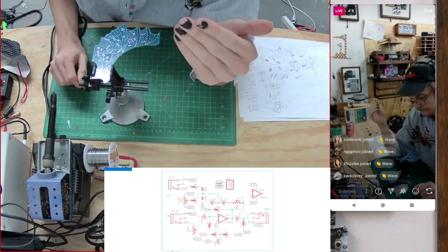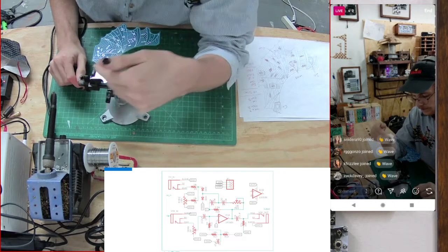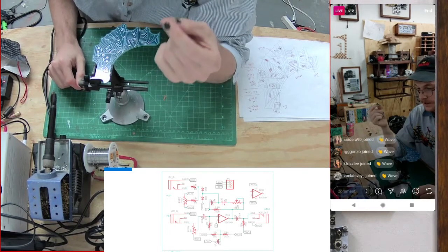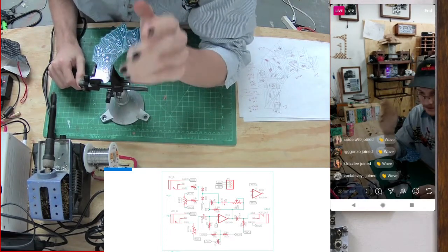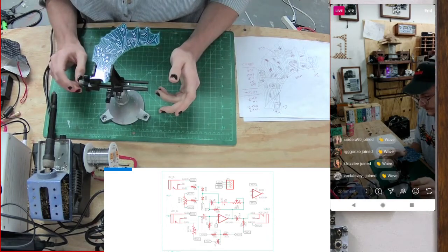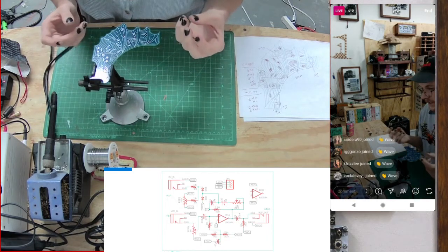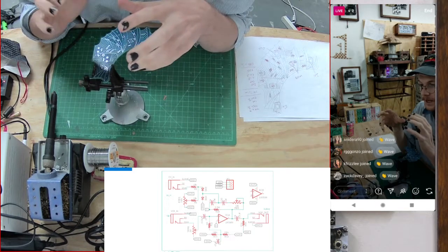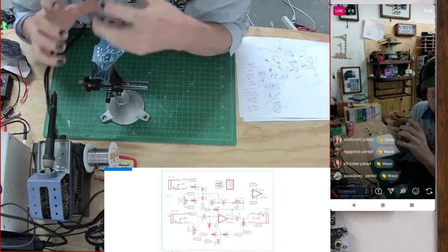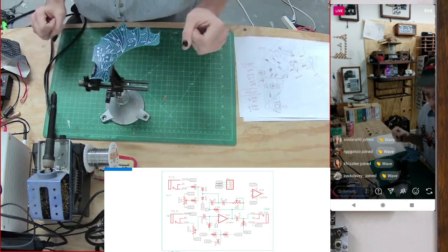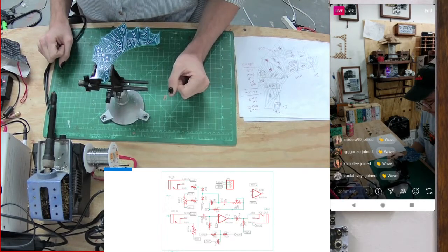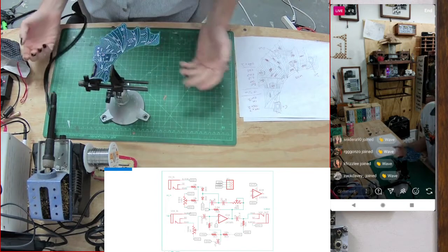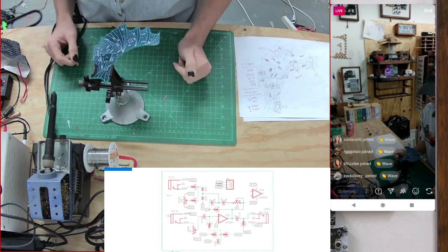What we're going to be building is a low pass filter, which is a really classic synthesizer sound module. It can take all the high frequencies out of your sound and give it a really good low bassy tone. Basically I'm just going to build this and talk about it as I'm building it.